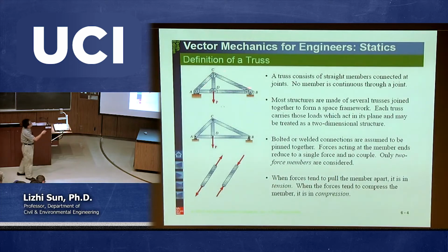So this is the truss structure having 5 slender members connecting each other, supported by a pin at point A and also a roller, or you can call this a rocker, at point B. In addition, there is a force acting on point D. So first of all, we do need to calculate the reactions as a first step.